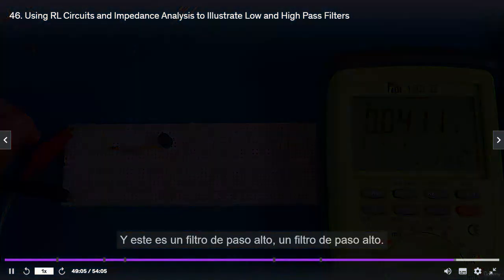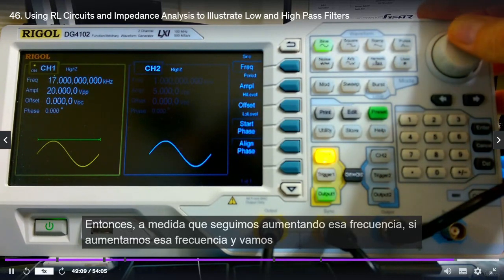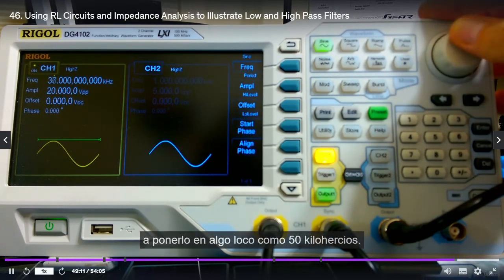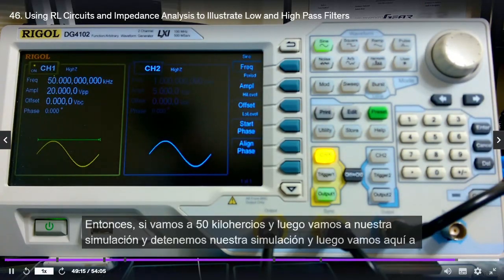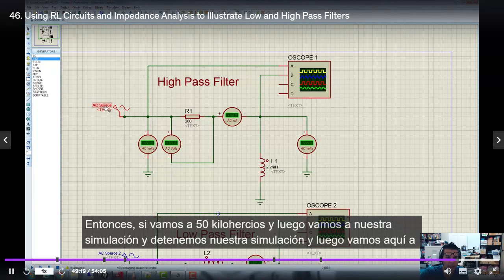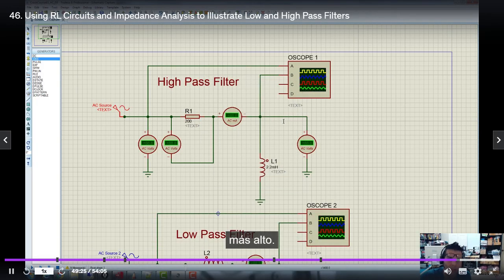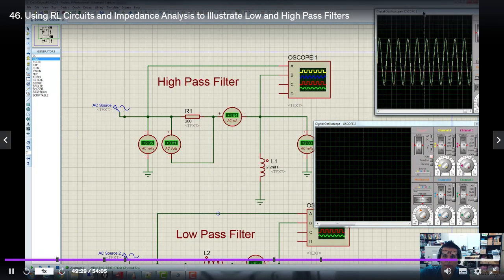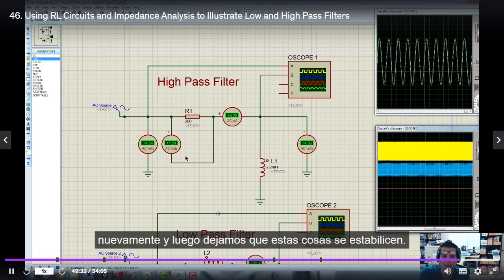A high pass filter. So as we keep increasing that frequency, let's just put it up to something crazy like 50 kilohertz. So if we go to 50 kilohertz, and then we go to our simulation, and we stop our simulation, and then we go here to the AC source, and we put this up to 50 kilohertz from the 5 kilohertz, an order of magnitude higher, and we run the simulation again. And then we let these things kind of stabilize.